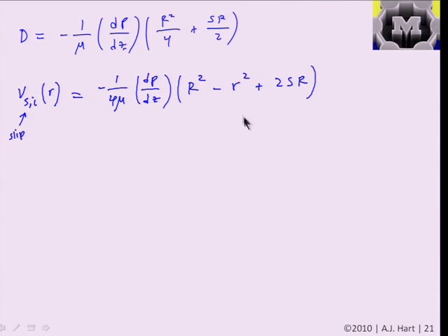And it means that this is effectively, quote, adding extra velocity to the whole profile. So slip has the effect that at the same pressure gradient, you're going to be able to push more flow through the pipe. And it's like taking all the fluid in the pipe and adding a constant velocity to all the streamlines. And that is just quantified by this term here.